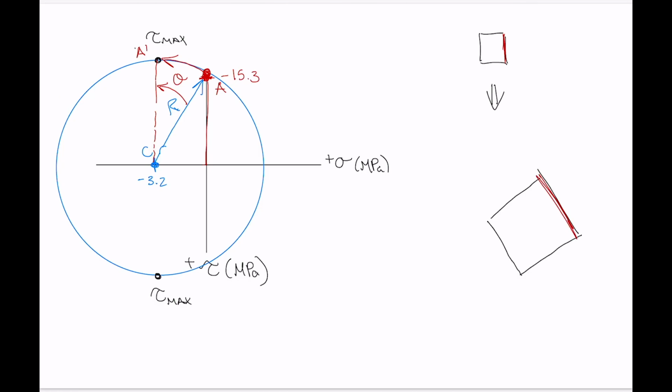So you imagine that it's pinned at this end here and has been rotated up. And if that angle that I drew on here was theta, then this angle here has to be 1/2 of that, because the rotations in reality are half of what they are on the circle always.